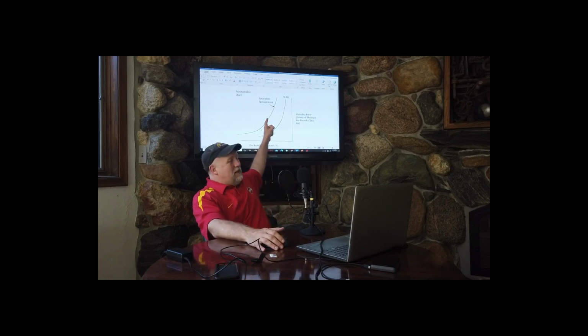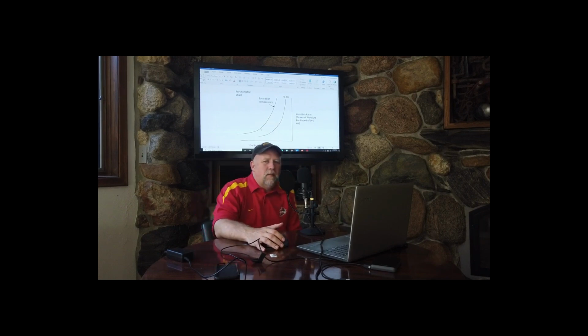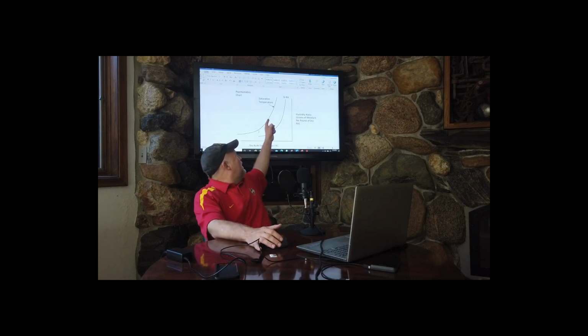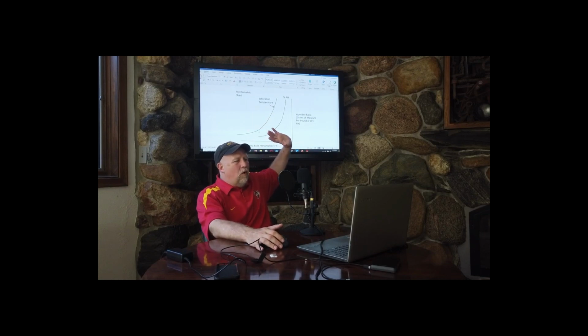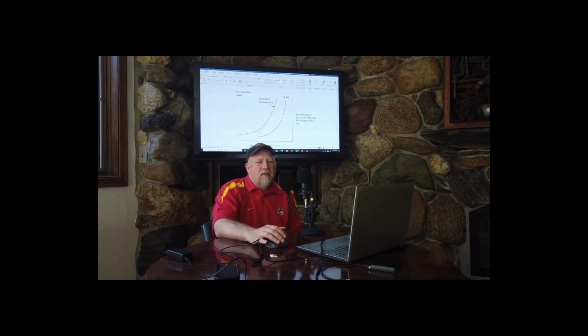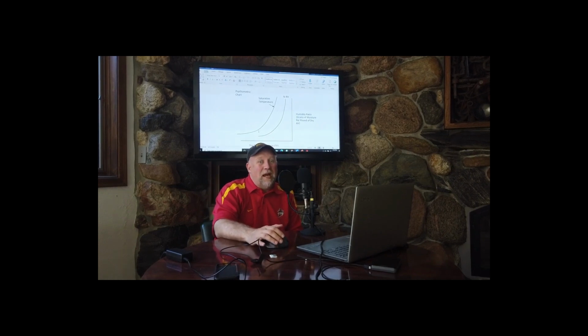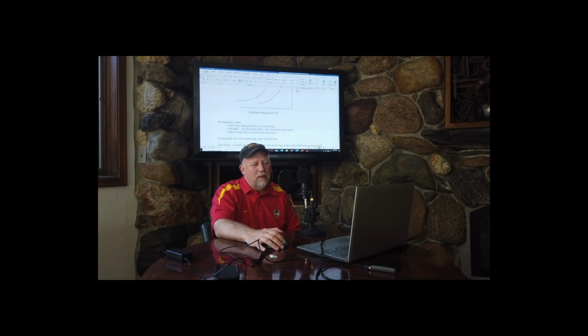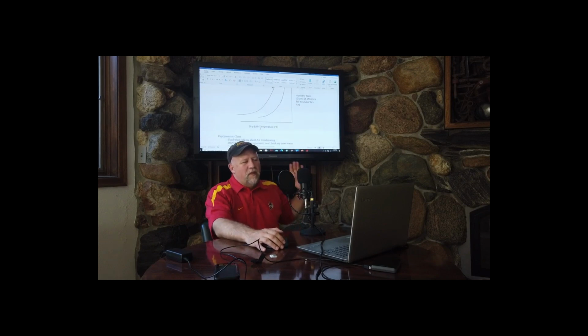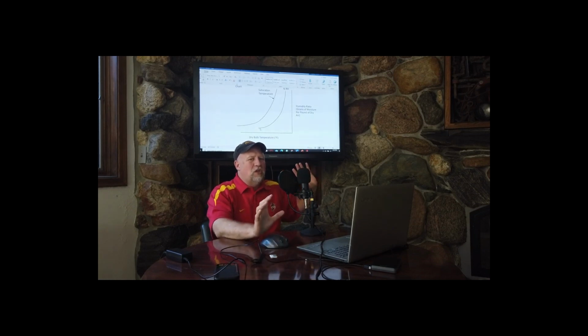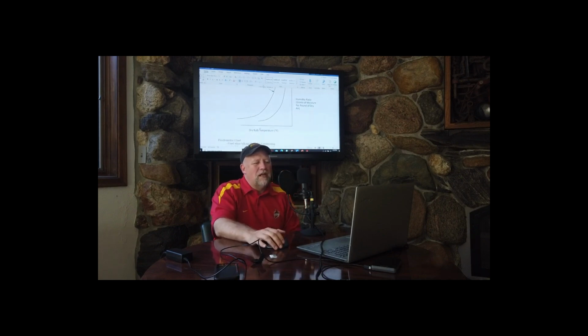Now, it doesn't go on forever. It ends here at the 100% curve or saturation temperature. In other words, this is it. This represents 100% saturated. The air cannot hold any more moisture. Think of that line as the point at which we start to get rain or fog. All right, now there's some more lines on here, but let me just start. This curve is what we will use to calculate the total change in energy as we go through a cooling coil. All right, the total air conditioning load.